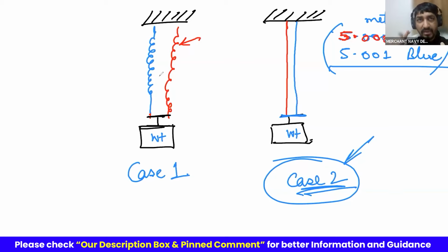Now coming to your other question, the other part, you said voltage should reduce. Well, yes, voltage also dips, and this is another concept where there must be voltage droop also. But the voltage droop is inbuilt into the voltage controller, not the governor. The governor is responsible for maintaining the RPM, so speed droop is part of the governor. What is a voltage controller, guys? What is the name of the controller of the voltage here? AVR. So the voltage droop will be inbuilt into the AVR.